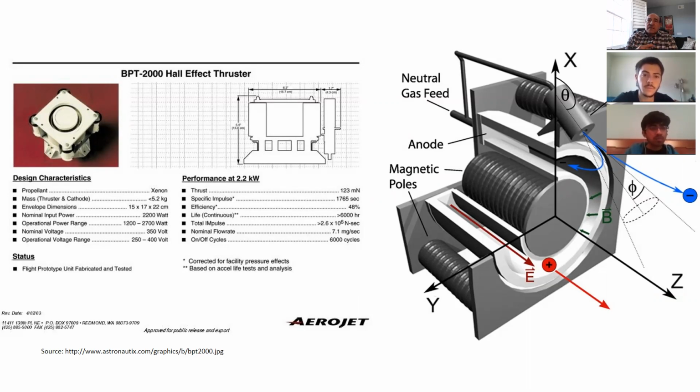One is the dielectric channels themselves. Here you've got some power, like 500 watts going there. What is the temperature rise and what is the stress that is to be expected, especially if we consider startup and shutdown of the Hall thruster? Is it continuous operation, or do they turn it on and off with that power going to the channels? So one thermostructural design problem would be the design of the dielectric channels themselves, from that number that you got. So that's one direction.